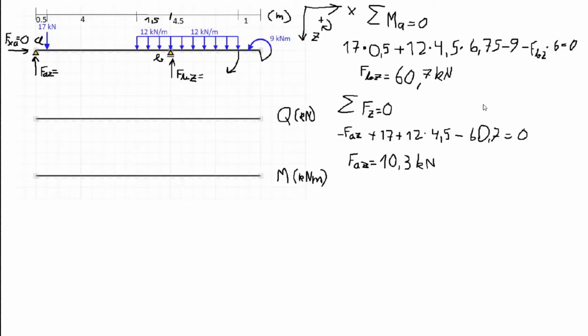Now let's move on to calculating our shear force diagram. In the shear force diagram we care about forces that move in the vertical direction. The shear force diagram shows what is going on inside the beam. So when a reaction force is pushing the beam up, it will create a shear within the beam that has the opposite direction but the same magnitude.